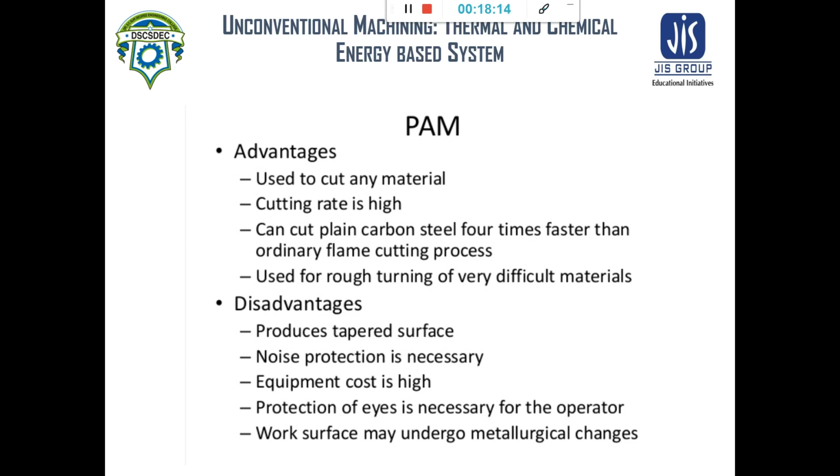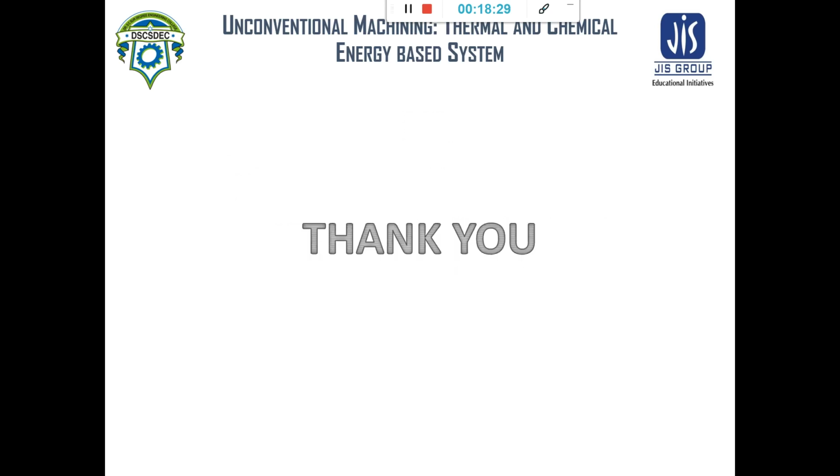Disadvantages: the process produces a tapered surface, noise protection is necessary, equipment cost is very high, protection of eyes is necessary for the operator, and the work surface may undergo metallurgical changes.